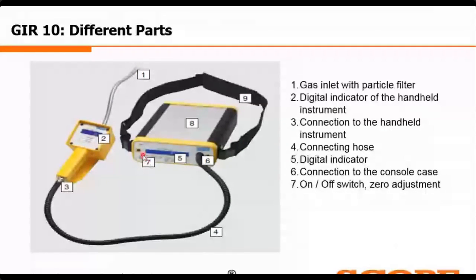For example, if you are doing leak detection of one compartment and then going to the second pole, for example, if you are checking the R pole of a breaker and going to the Y pole of the breaker, you can do the reset here. The sensor will automatically reset the value, and you can check the Y pole of the breaker as well.